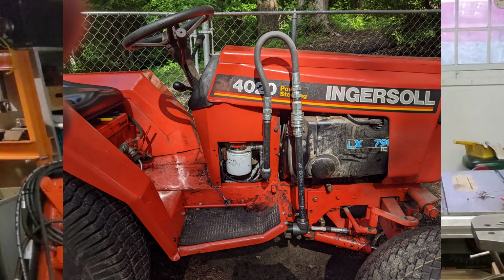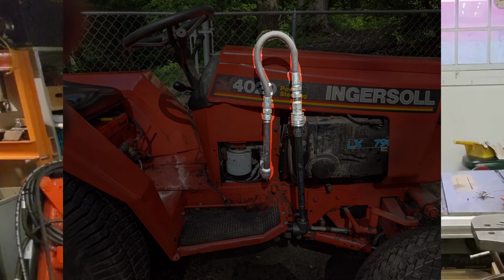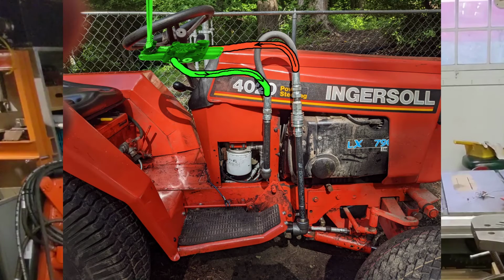So now there will be two quick disconnects in the vicinity of the right side footrest: a lower outer one that'll be 2000 psi high pressure, and an upper inner one that will be the low pressure return. With the loader attached, you'll just hook up two hoses to the new loader valve, one to supply it and one to return from it.